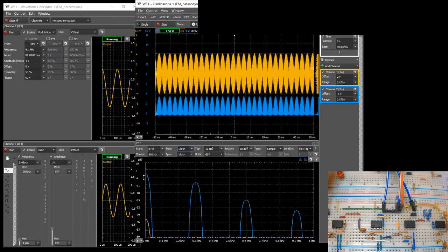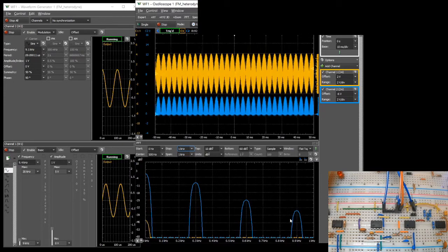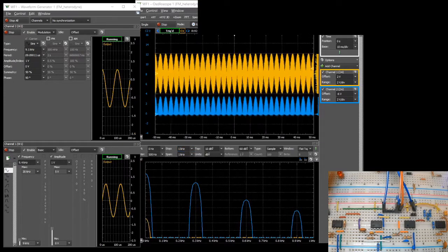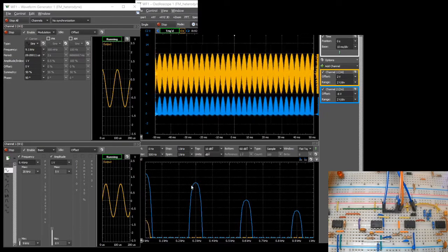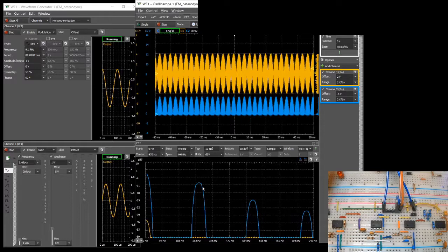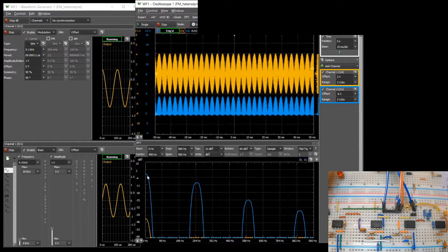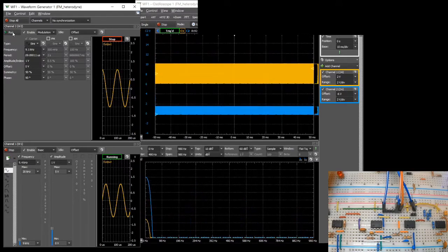A close-up of the low-frequency portion of the Fourier spectrum shows the main and only nonlinear mixing component of interest. It is the absolute of f2-f1 component, which is the heterodyne signal. The DC component, the line at zero frequency, is not a nonlinear mixing component, hence it is not desired and will be filtered out later.